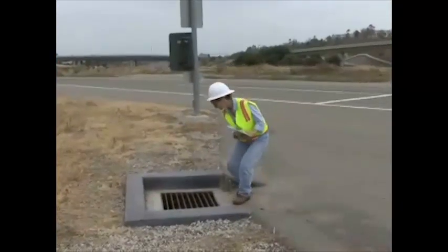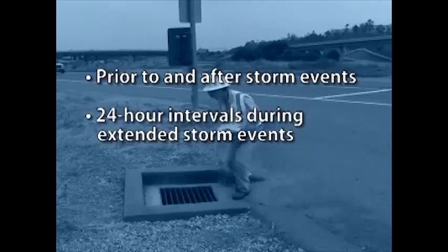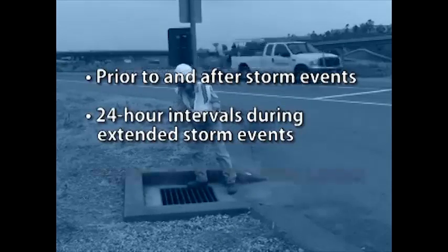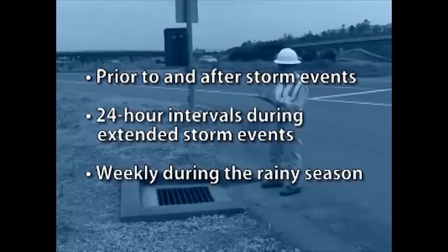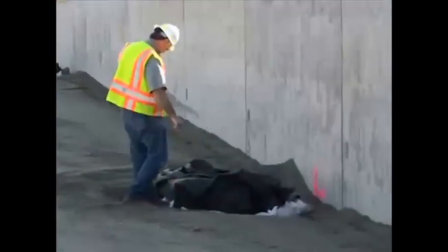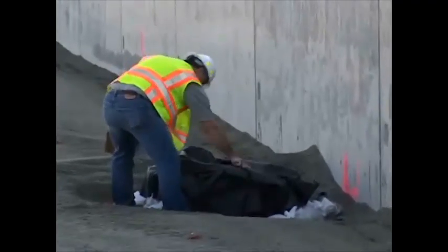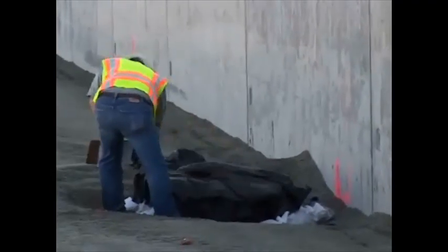Inspect all inlet protection devices before and after storm events, at 24-hour intervals during extended storms, and weekly during the rest of the rainy season. Check storm drain inlet protection devices after several storms to assess if sediment is bypassing inlet protection devices. The contractor's water pollution control manager should also check for sediment accumulation.